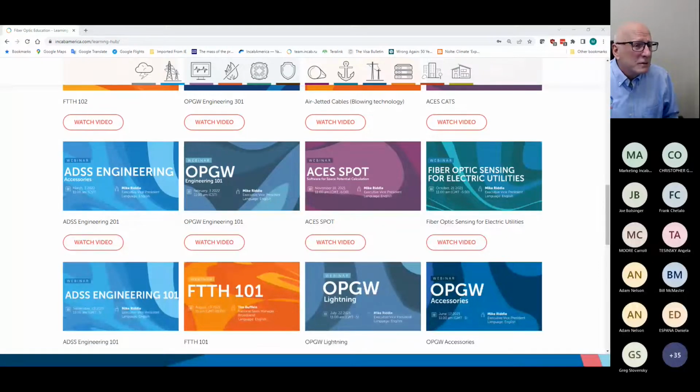Drop cables are relatively small, and so everything has an impact on the real overall strength of the cable, including the jacket itself. With just ADSS, usually it's your aramid or your strength element that's really giving you the strength. The center member, it's often called a strength member, but I consider that a poor use of terminology. I think of it as more of an anti-buckling element, not really contributing a lot of strength.